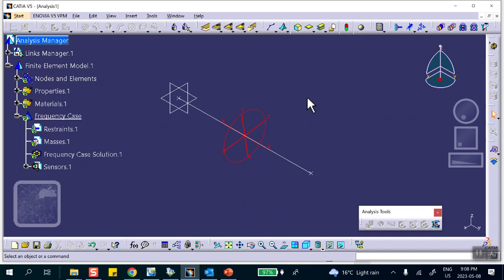Let me put it this way, because remember, I took the Young's modulus of aluminum, I'm sorry, from 10 million psi, I made it 0.1 psi. And that density of it, I made it 10,000 times smaller. So you'll have no effect.